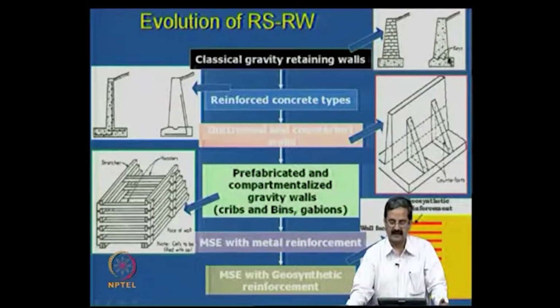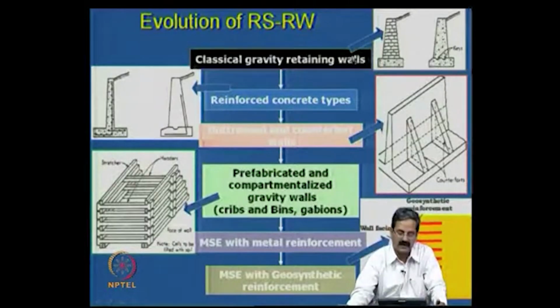So we design this, and sometimes when it is required, we try to provide shear keys also to increase the shear resistance, because when there is a lateral force acting, there should be some resistance provided. Either it can be shear keys here, or sometimes even at the bottom. So that is one concept for gravity retaining walls.